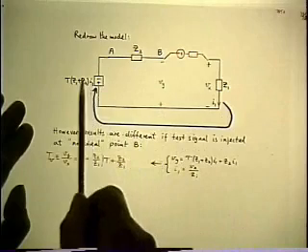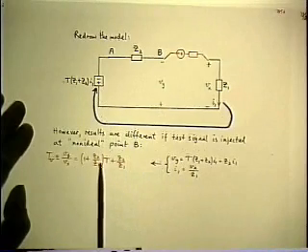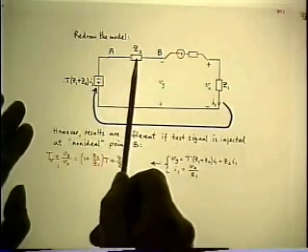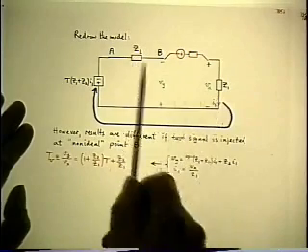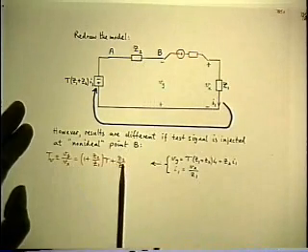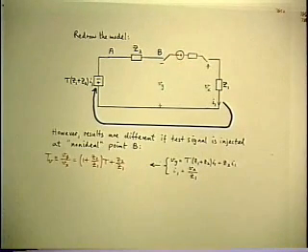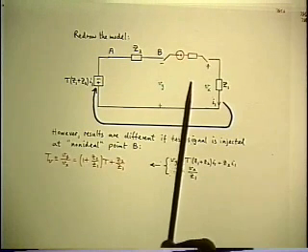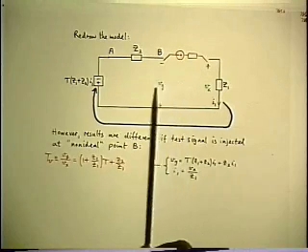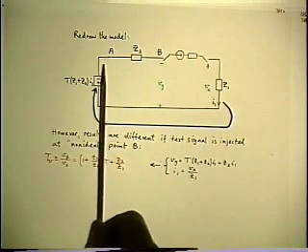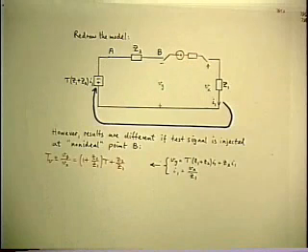So what I do is I evaluate this generator in terms of Vx, and then I subtract the drop in Z2, which I also know in terms of Vx, and this is the answer you get for Vy over Vx. Well, we were unlucky. It isn't T. So you get the wrong answer for measuring Vy over Vx if you can't get to an ideal injection point.